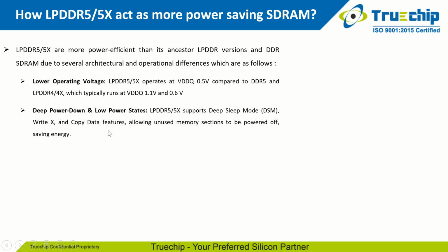Power saving can also be achieved by a faster and less complex frequency change operation, also called the FSP change procedure, which changes voltage swings and termination value without ever being in an untrained state, which could result in a loss of communication to the DRAMs. Frequency set points allow the LPDDR SDRAM CA bus to be switched between two different operating frequencies. This is achieved by duplicating all the CA bus mode register parameters as well as other mode register parameters commonly changed with operating frequency.